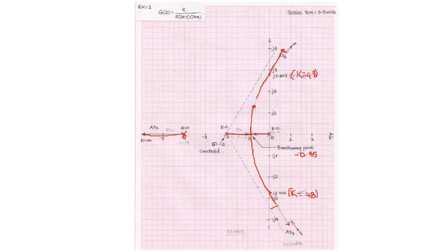K tends to infinity. It means here the K value is going to go from 0, 1 to some value. At this particular point, if you substitute, whatever K value you get, the system is going to break, and for all lesser positive values it will remain stable. It means on the left half of the s plane, this side, it is the stable zone. And the right half, after crossing this K margin or marginal stability line, will be an unstable zone. So I have written here stable, unstable. So for stability to remain in the given problem, we should have the system with K value lesser than the margin. Okay, this completes your first problem.